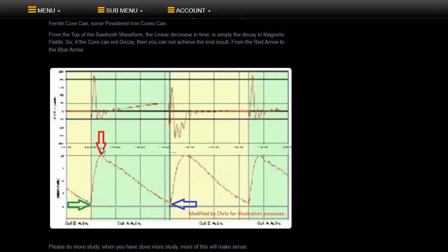When we drop back to two magnetic fields, our output becomes a linear decay of energy generation. So this is a collapsing magnetic field between the two coils, peak magnetic field up here. And remembering this is voltage, not current. Because we've got a resistive load on the output, the voltage and current are almost in phase, almost 0 degrees from each other. There's no phase angle difference, and the coil itself has a current which would almost look the same.